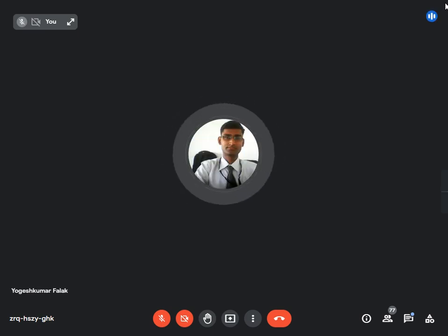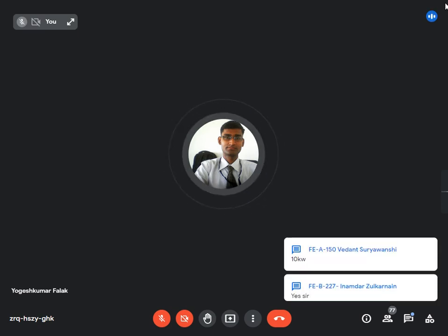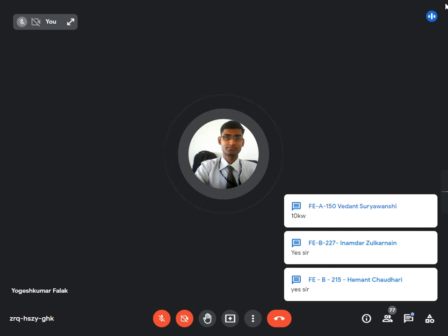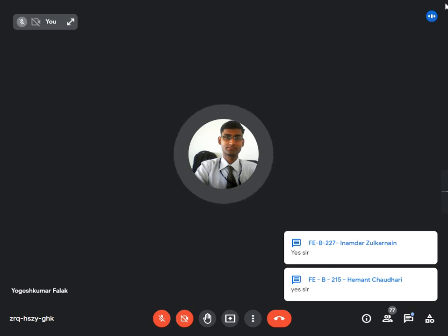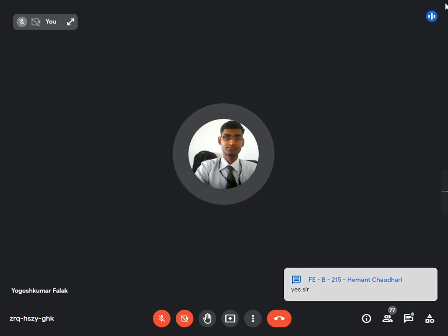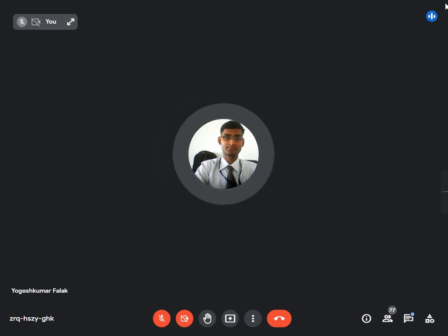The only change you have to do here is to change the value of Q2, that is 360 kilojoule per minute, to 360 by 60. So it is 6 kilojoule per second. Using the formula of the COP, you calculate the power input W. So 6 by 1.5, you get W equal to 4 kilojoule per second. By the first law of thermodynamics, W is equal to Q1 minus Q2, and to get Q1 you add W plus Q2.